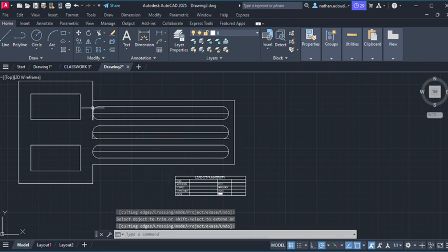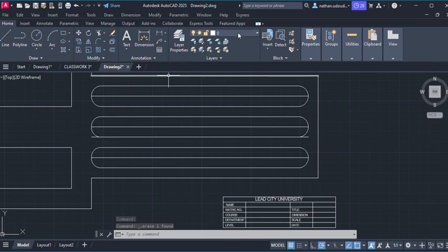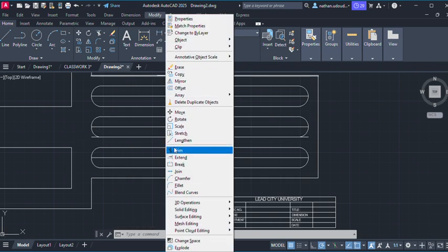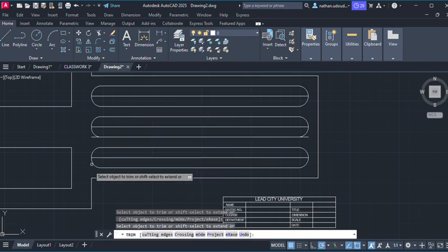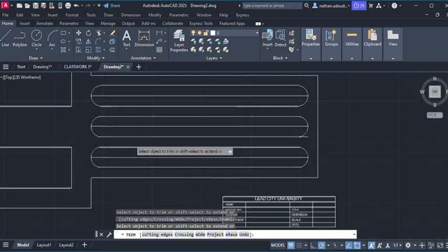So this you don't need. You highlight and delete, press the delete key. You also highlight, delete key. Okay, so you need to trim this. So you come to your modify toolbar, trim, right click, and then left click on this.